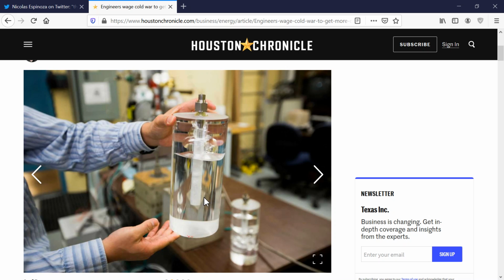And I'll try to get these videos. If I can get these videos from Minsu, I'll share this with you. But basically, when you start injecting liquid nitrogen, even if you're not above the fracturing pressure that you would need without a temperature shock, you will start creating fractures due to the local shrinkage of the solid.